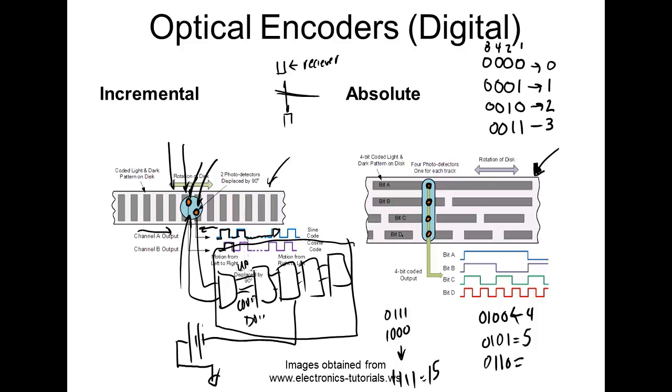And these batteries have got to be in the robot, because when they ship these things, the robot and the controller are not in the same box. So I need to have the ability to remove the robot from the controller and still have the robot maintain its origin. That's part of the preventive maintenance on most robots: going out there once a year usually and doing what? Changing those batteries.